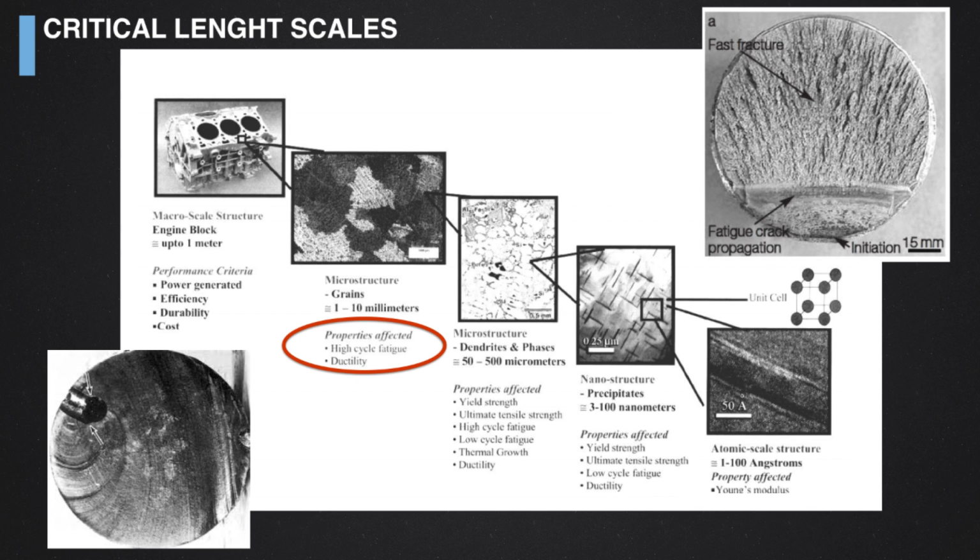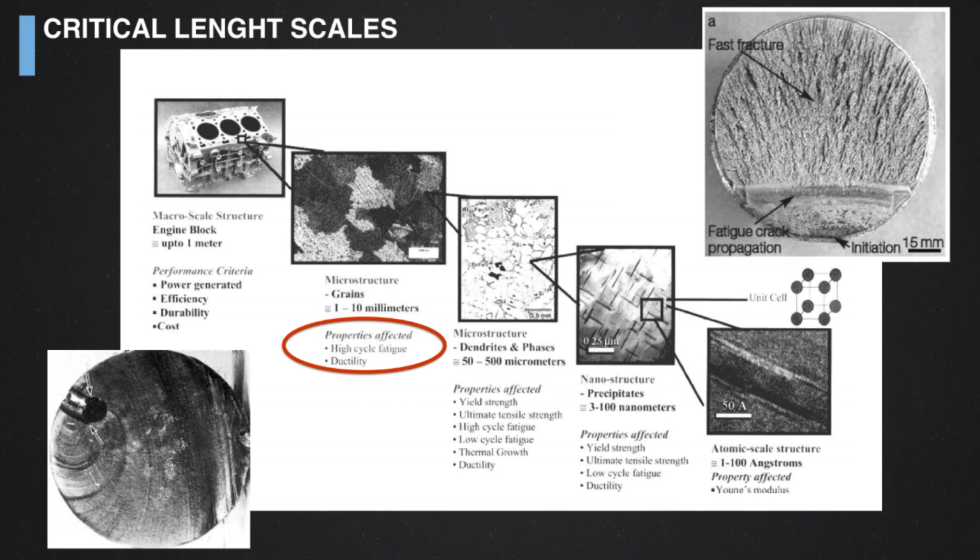So what happens is that normally the fatigue fracture starts from the surface of the material. When there is a flaw in the surface, so the surface is not perfectly smooth and even, the stress propagates from that flaw, and cyclically the crack is further expanded until a point where you have reached the maximum strength of the material, and it breaks dramatically in a fast way, in a so-called brittle fracture, and you can clearly see the difference between the two regimes of the propagation of the fracture.